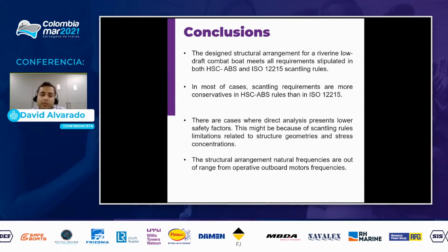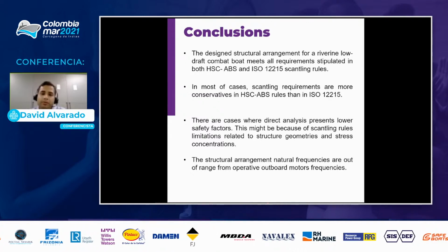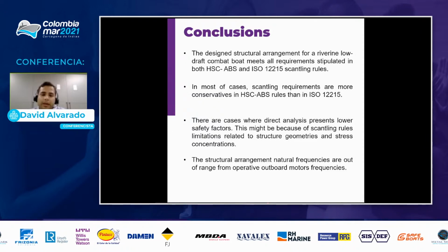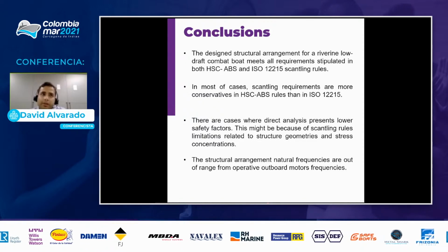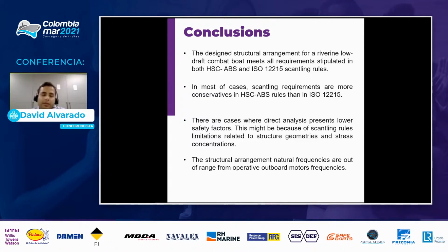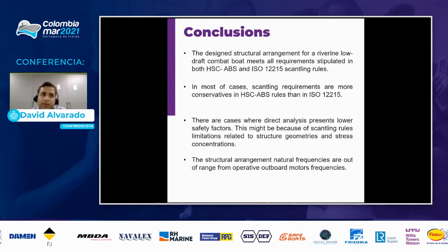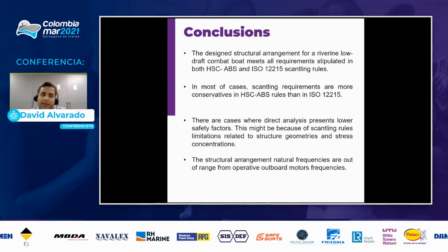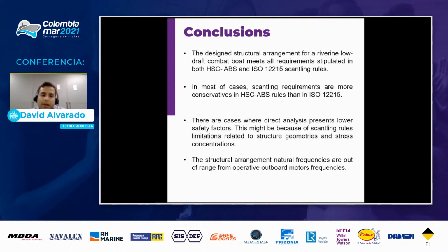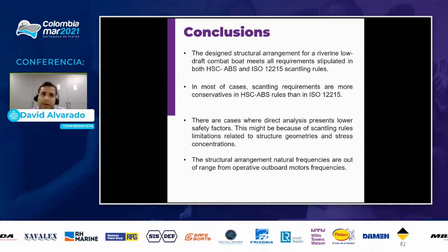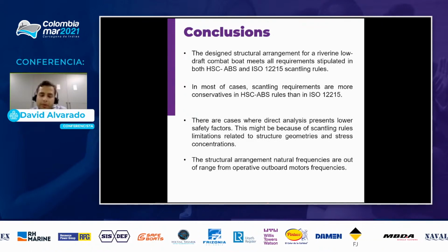In the majority of cases, the requirements for scantling are more conservative for the high-speed craft standard from ABS, and the direct analysis, despite the fact that in the majority of cases it shows how conservative the evaluations are on the basis of standards, there are some cases where they are more critical according to the direct analysis. This shows that there are certain cases where the considerations are actually far from reality.